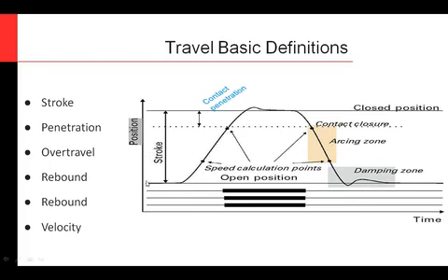One thing I'll mention on this, so open position, closed position, open position. These three lines here are actually our timing. So a thin line is actually open. Then as soon as the breaker comes closed, it's a thick line. And then as it comes open again, it goes to a thin line. So this is a close-open type operation.